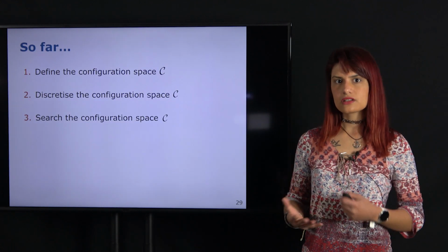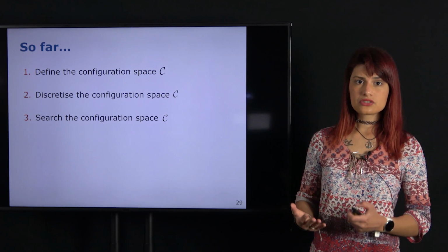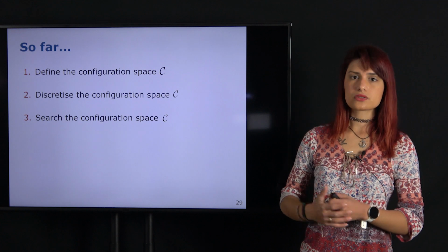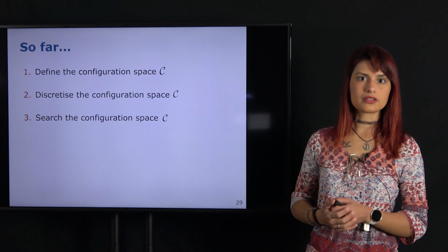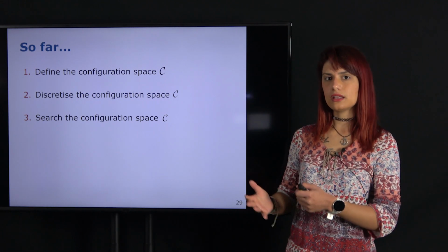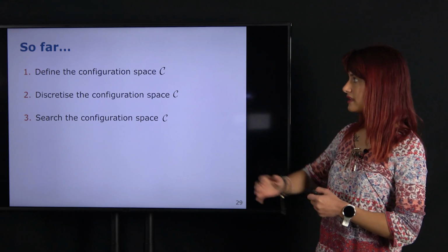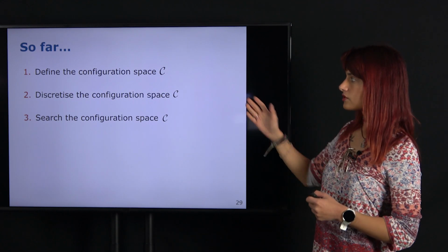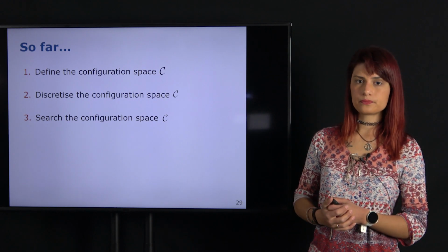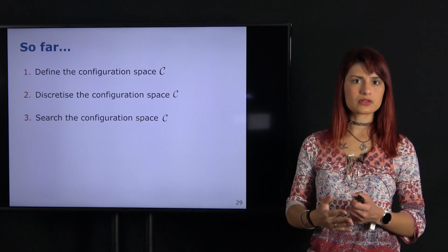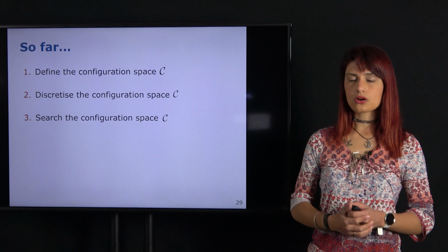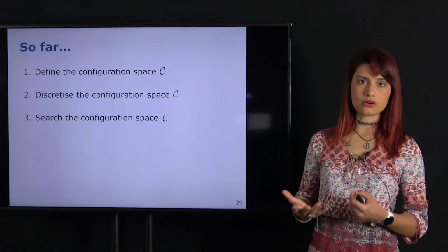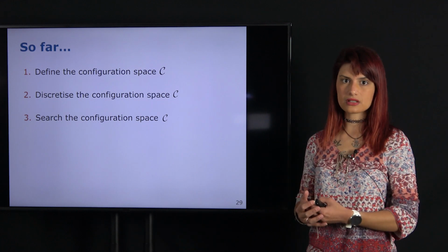So now is a good time to take stock of what we have covered in the previous slides. So in general, the approach to solving the planning problem has been we need to somehow define the configuration space. So is the robot moving in 2D or 3D, and what is the minimal number of parameters that we need to fully specify its configuration in the environment? Then this gives us a continuous and dense representation of the configuration space. So then what we want to do is discretize the configuration space in some way, and look at different ways this can be done. For example, we can create a roadmap using one of the geometric methods, or we can overlay a grid on the environment and apply grid-based planning. But in general, the purpose of this step is to convert the continuous into a discrete, concise representation so that we can do planning.